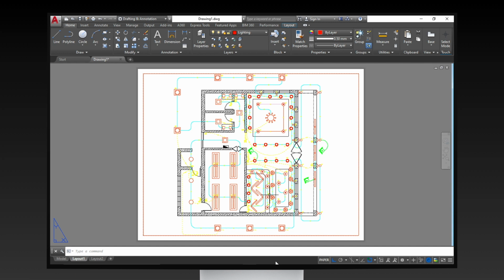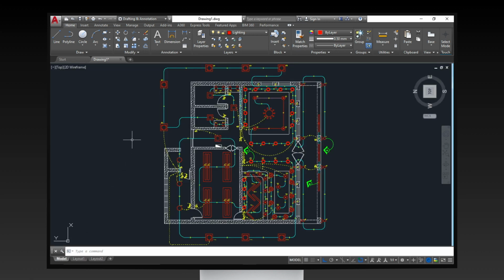paper space. When paper space is activated, objects drawn will be exclusive to the layout you're drawing it with. It will not be seen in the model space even though the objects are drawn within the viewport. On the other hand, objects drawn in the Model tab will be seen on the Layout.